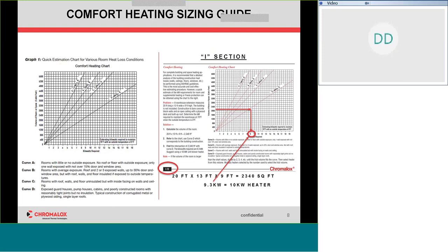And you can take this chart and this graph, and it's in the I section in the back of the catalog too, page I-12. They say, look, we're looking at maybe a 10 kW heater based on your 3,400 square foot area. These are really quick reference guides, and it's good to know that they're there. Some people knew they were there, some people didn't, but this gets you started down the right path, not only for yourself, but for your customer, getting them in the right mindset.